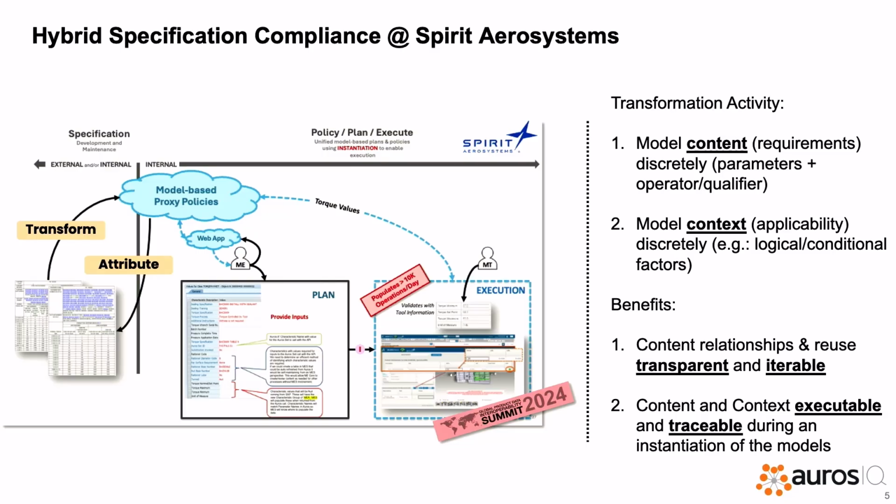So that's obviously problematic because what really happens, right? So we're back to the informal. Oh, Joe told me that's 30 inch-pounds. Whoa, what? So if we come back and audit, that's a problem, okay? So you say, well, go look it up. Well, depending on the specification, there are many tables in the specification. There's no nice way to correlate fastener combinations to the table in the specification. So even if I tell them to do it per the specification, that's problematic, okay?